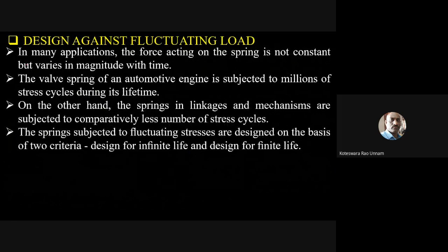The main reason why the magnitude of the force is varying is because you are using the spring in such applications. Or else, take an application in automobiles where springs are used in a suspension system. There also the load is not constant. Depending upon the road bump, the magnitude of force will change. So there also it is there. And of course he has given these applications here.